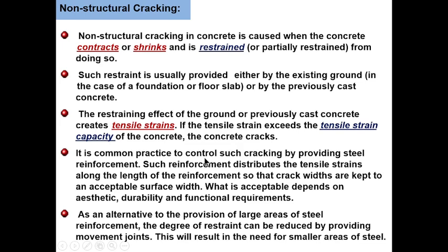So let's look at non-structural cracking. Non-structural cracking in concrete is caused when the concrete cracks or shrinks and is restrained from doing so, either fully restrained or partially restrained.